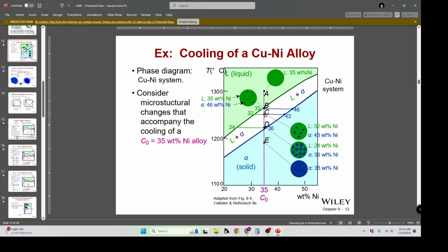into ice as it cools. More of the copper condenses into solid. So 43% is now the nickel composition in the solid. So the nickel composition goes down as you go all the way down to this range. So it'll reach the same 35% composition. This is just above that solid line, because at the solid line, it's 35%.